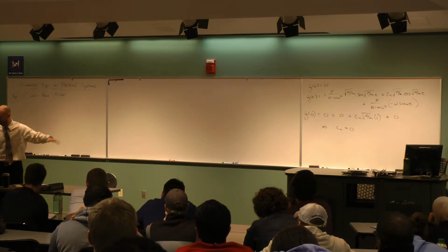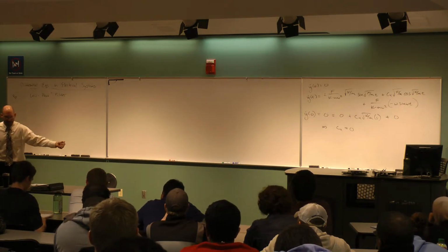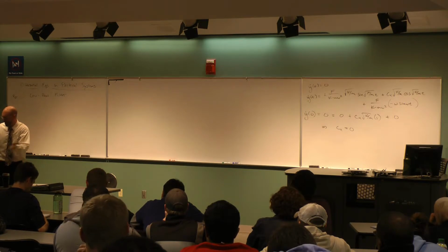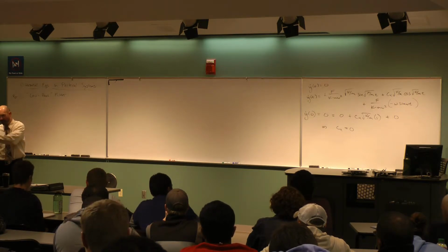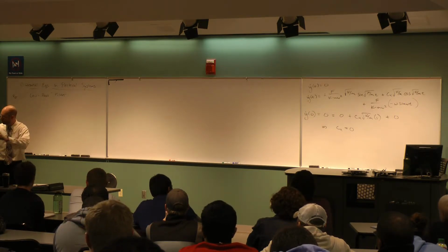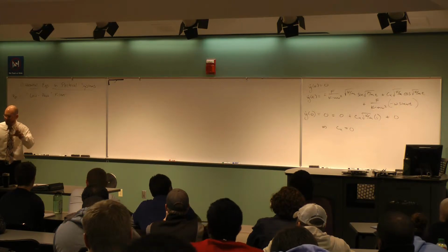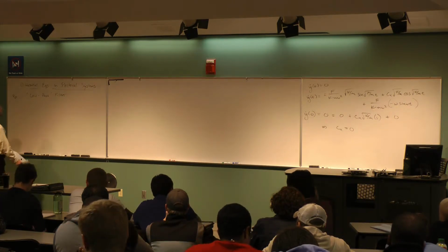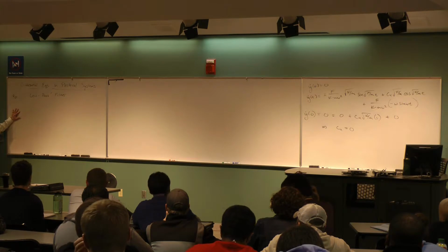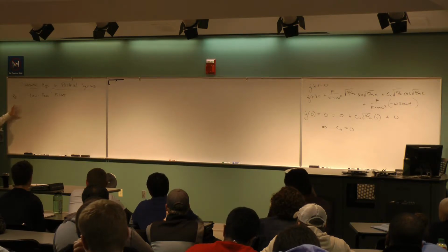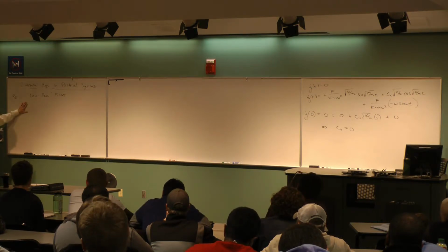And try and keep the noise down, get clear sound, those kind of things. In an electric circuit in general, I can think the same way about output voltage, output current compared to the input, trying to get the noise out of the system. When I want to get noise out, whether it's low frequency noise or high frequency noise, I want to put filters electronically in the circuit. Okay, and this is an example.